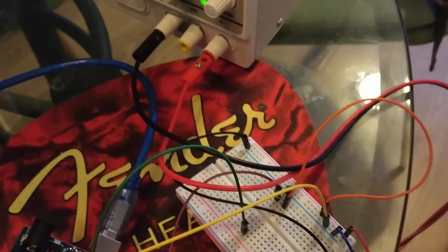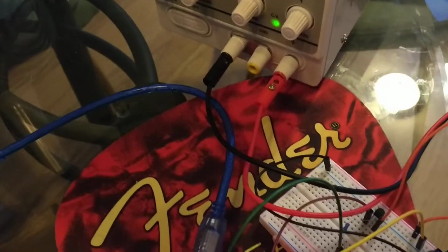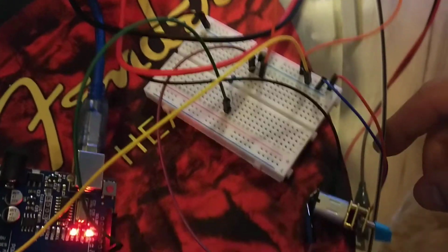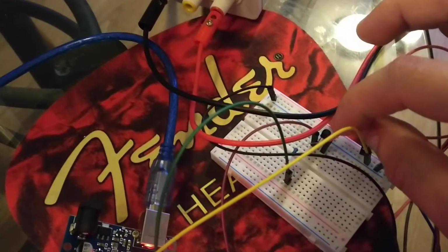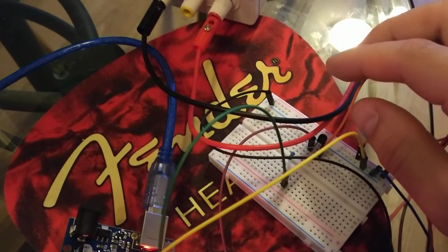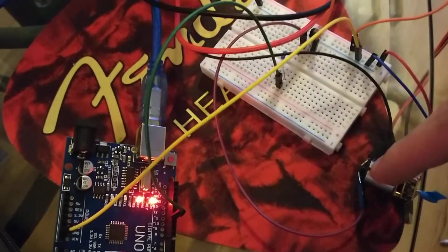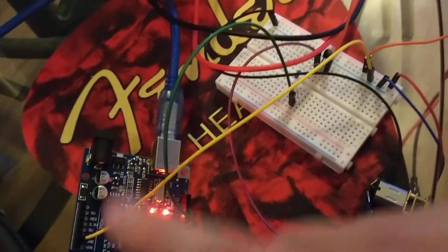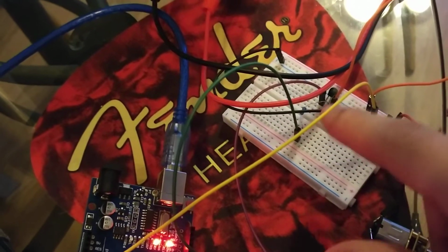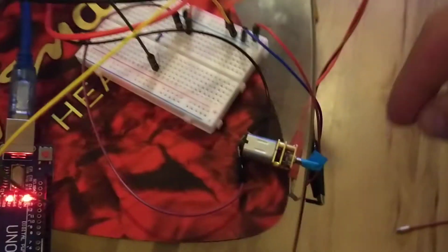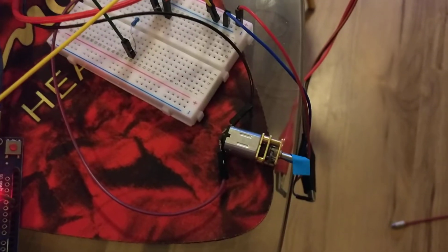From here, we are going to have it hooked up to a 6-volt power supply. That's going to be going over here to the positive and negative leads on the proto board. And then from there, we are going to be taking our positive going to one side of the transistor, the collector, I want to say. And then on the other side, we're going to go from the emitter, and that's going to go to the motor. So what's going to happen is the Arduino will be sending that PWM signal to the transistor, and then that's going to be opening up and allowing more voltage to flow through. So you can see right there, it's kind of spinning, but slowly.